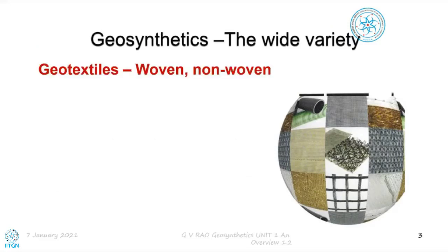So in the beginning, we thought that there are certain standard types. Let us say the first class of materials we said is going to be geotextiles, but geotextiles is a class of materials. Actually, we call it a generic classification. That means we are not making a product from a company, we are talking of generic products now. By generic name it is geotextiles, but we find later that the geotextiles are not one material. Probably it will cover 3 types. I mentioned 2 only here: the woven geotextiles and non-woven geotextiles.